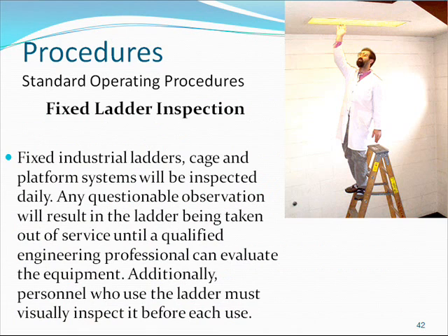Fixed ladder inspection. Fixed industrial ladders, cage, and platform systems will be inspected daily. Any questionable observation will result in the ladder being taken out of service until a qualified engineer or professional can evaluate the equipment. Additionally, personnel who use the ladder must visually inspect it before use.